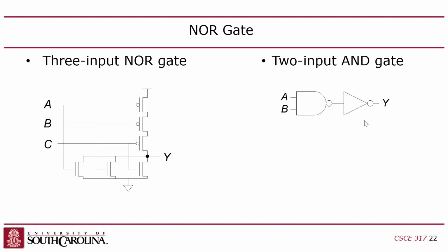Make sense? So I need to have a negative voltage on the gate for a PMOS. Why? Because I got to attract the minority charge carriers in a PMOS, which are holes. I got to get holes in the channel, right? So that's the reason why I got to have the PMOSs in the pull-up network, right? And the NMOSs in the pull-down.